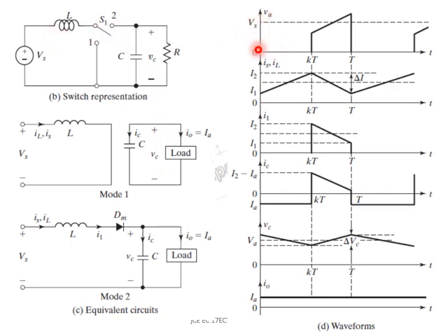In this diagram, we are looking at the output voltage VA that is coming across the load. It's a resistive load, and we see that from 0 to T on, or from 0 to KT, the output voltage is 0 because it gets disconnected from the input. During this time, the inductor current rises from I1 to I2. We are considering the inductor current to be a continuous load current, and it goes from I1 to I2, like charging this inductor.